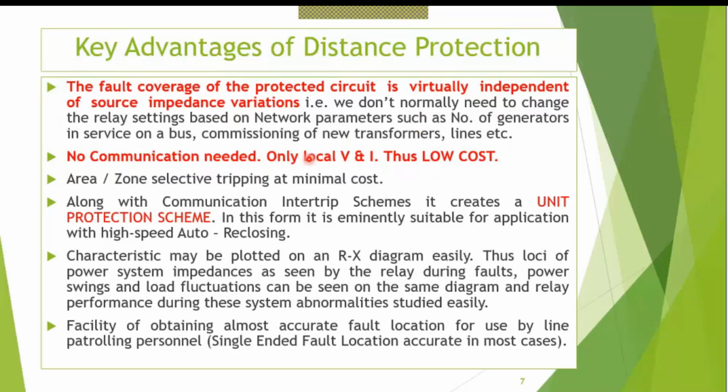No communication needed. That is why it is low cost. Line differential is of course the best form of protection. Those who are a bit old in protection, everybody knows line differential is the best, because there is no falsifying in the line differential. But the problem with line differential is that high cost is involved, because the remote end current parameters have to come to the local end. Only then can the differential protection be activated. That involves a high cost.